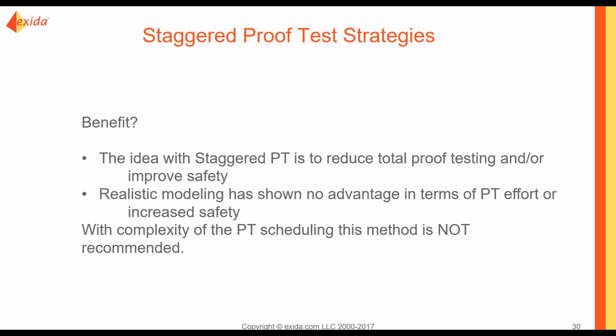Although this method has been proposed as a way to reduce total proof testing and or to improve safety, realistic modeling has shown no advantage in terms of proof test effort or increased safety. Given the added complexity of this proof test scheduling, this method is not necessarily recommended.